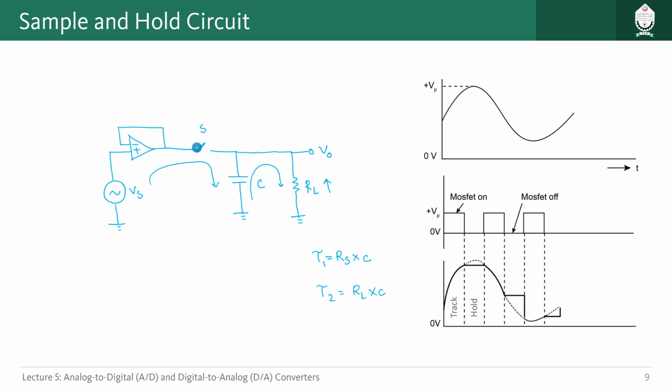And the configuration we have is called buffer. In this configuration, we know that whatever input voltage we have provided through the positive pin, that should come out at the output, right? So whatever we are providing, we are getting the same thing. But what benefit are we getting from that?